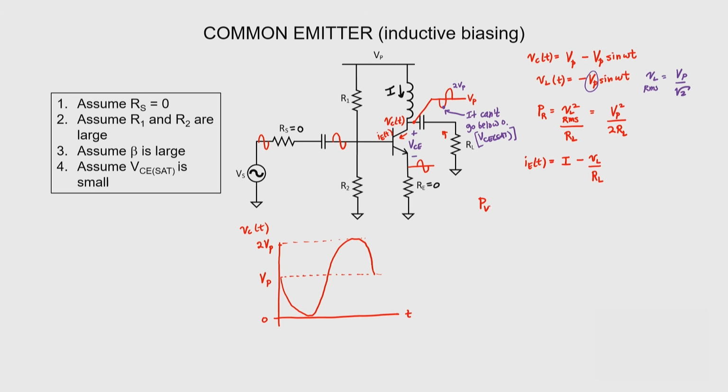Let's now find the total power supplied by the amplifier. We'll call it PV. So let's integrate again over one period. And we need the voltage times the current. Well, the voltage up here is just constant. And the total current supplied is given by I, coming up with a final expression of VI. The efficiency of this amplifier is given by the power delivered to the load resistor divided by the power supplied to the amplifier. Let's simplify that just a little bit.